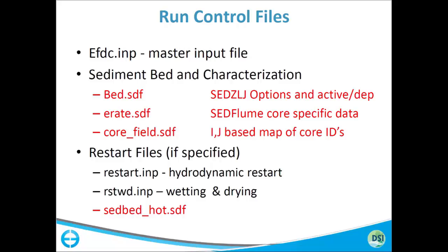That's just a little note here. If you're ever running a real project, don't ever run a model without turning on the restart file option. It doesn't cost anything computationally, and from a size perspective, it's usually negligible. Just check that little box and say I want a snapshot every day. That way, if something happens to the model for whatever reason, you lose power at the office or something, you can just restart the model, use EE.